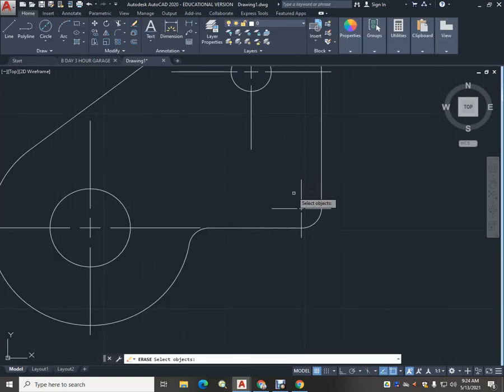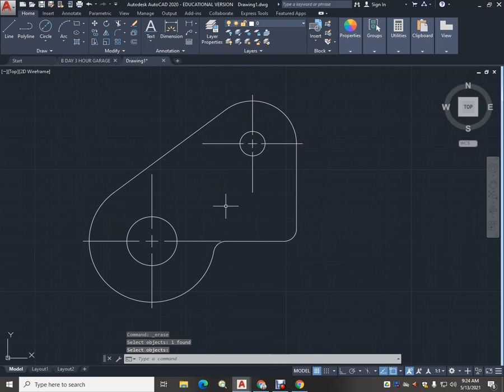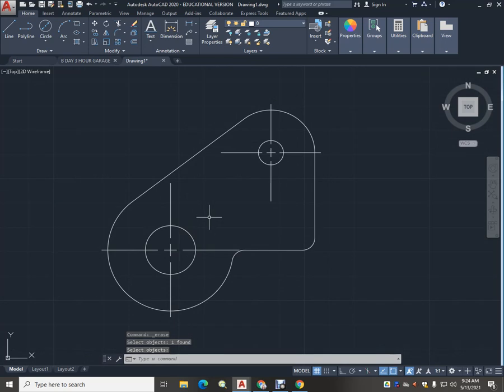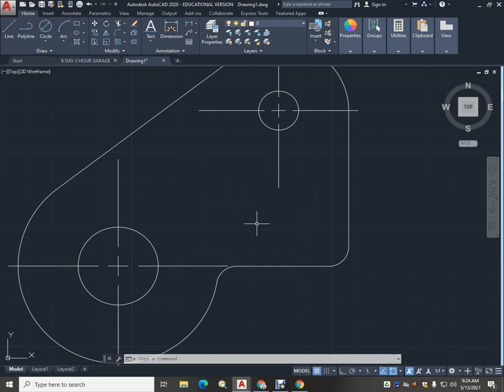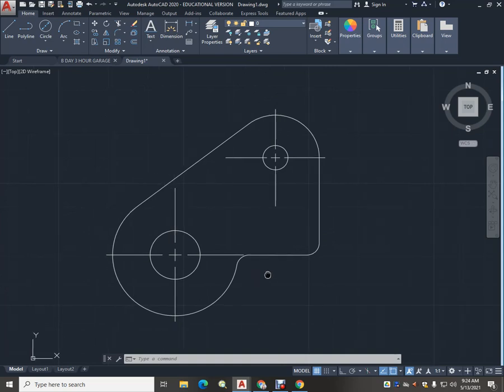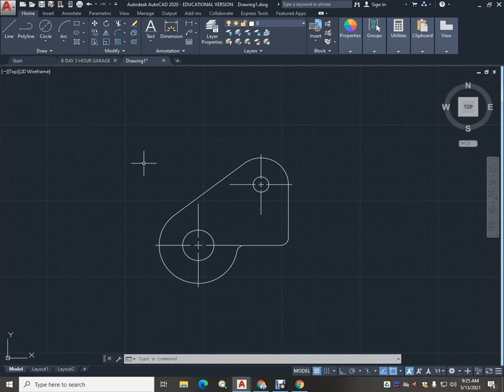So as we look at different things, I mean, there's a lot of different rules. Mostly our center mark is related for larger pieces like this. Anytime that you put a radius and diameter, consider that you follow by a center mark. Anything created by a fillet, 9 times out of 10, doesn't require a center mark. All we need to do is put that dimension in, and that would make everybody happy. That would make our machinist happy. So let's go in and put some dimensions.